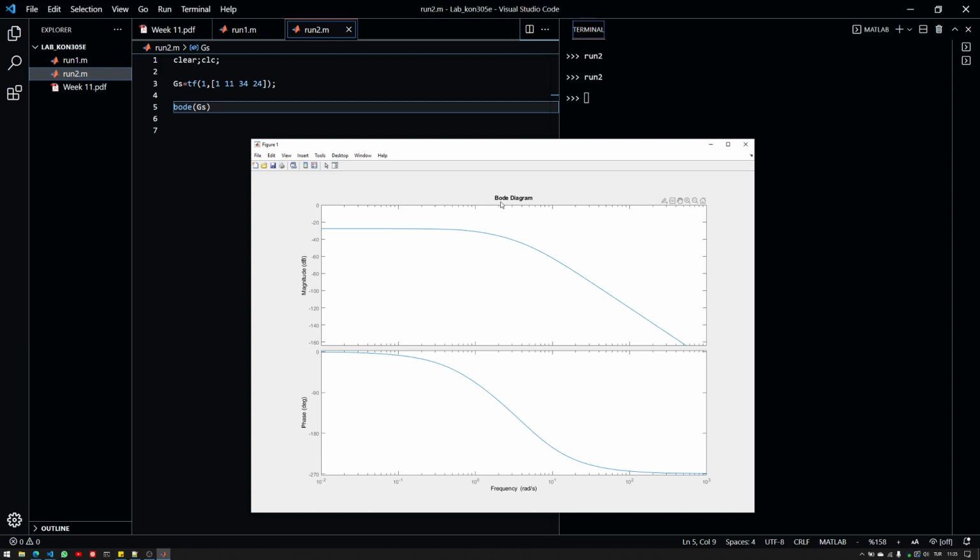So if you deal with the Bode diagram, you have to make a little conversion here, because this is like minus 20 something decibel. So what does it correspond to in terms of, let's say, gain? So this is the gain, or the magnitude of the Bode plot, by the way, and this is the phase angle of the Bode plot. Now, these two pieces of information are tied together with the omega axis.